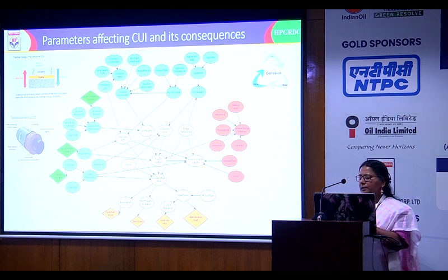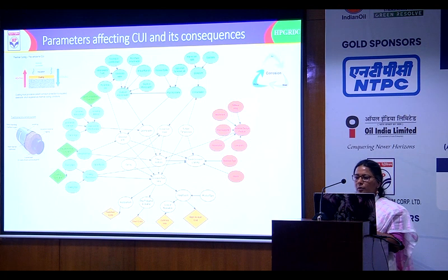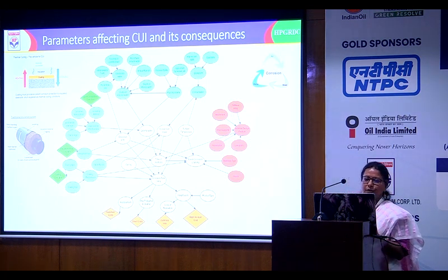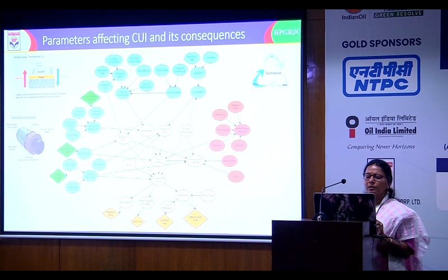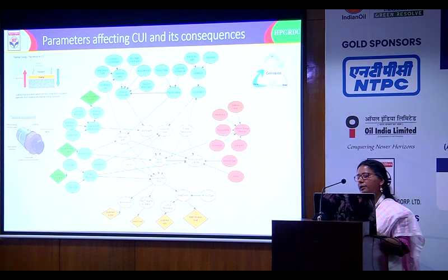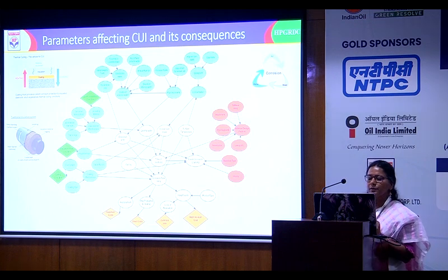It permeates through and settles on the metal surface, and at the 6 o'clock position where there is contact of water, the corrosion under insulation will occur. So this combination of air, steel, and water will lead to corrosion under insulation. Based on this, the consequences, as we all know, are direct corrosion loss or indirect, in terms of the company's reputation and production losses.